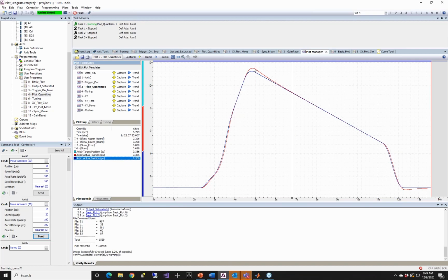So if I plot these two together, you can see that there's a skew between these. I'm going to show you what the skew actually looks like. This green line here is the skew. So you can see as I get farther away, my skew will start to increase and decrease. I want to be at this line 0 right here. You can see I go negative in some spots and I go positive in others. This would tell me that I probably need some tuning on my system.